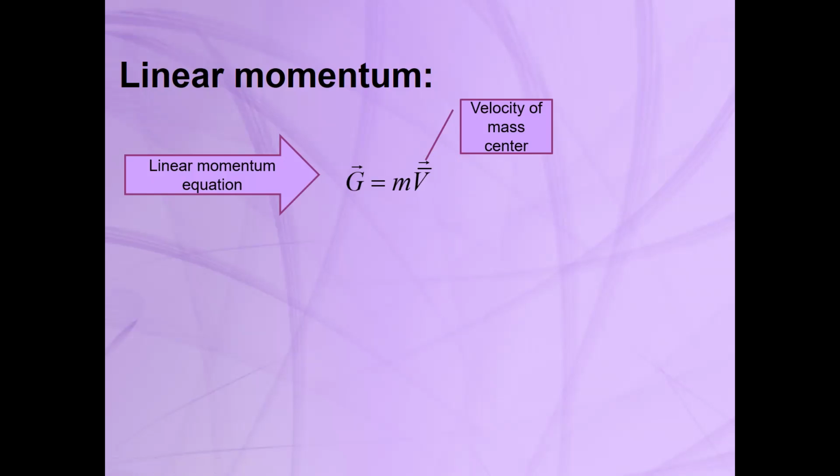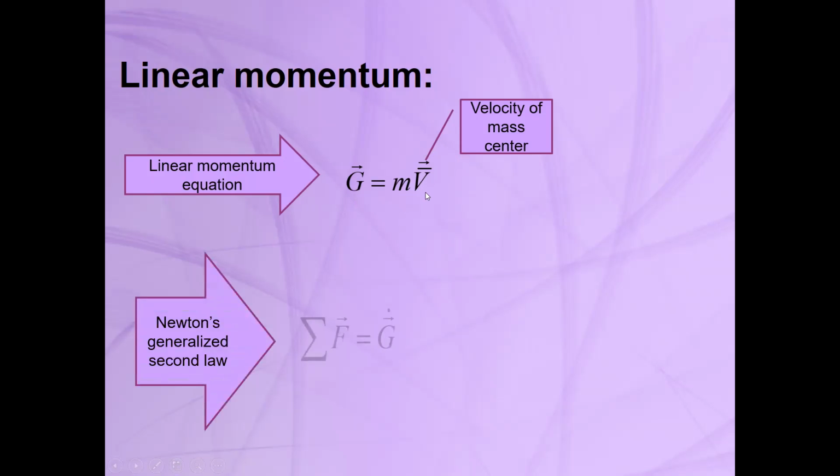So in the rotational motion it may be different, but when you want to calculate the linear momentum, this is the linear velocity of the mass center. Okay, so you should note that this is maybe the difference between the linear momentum for a rigid body and a particle.